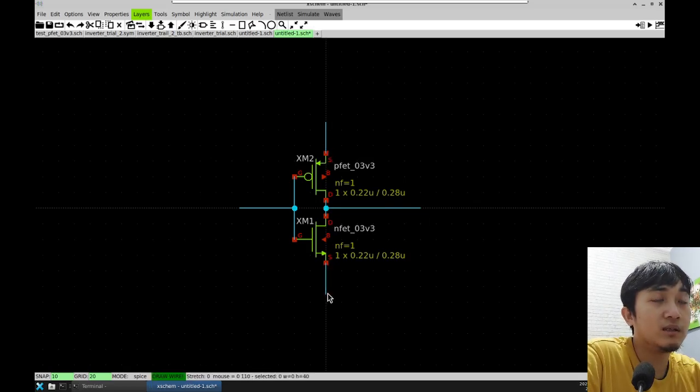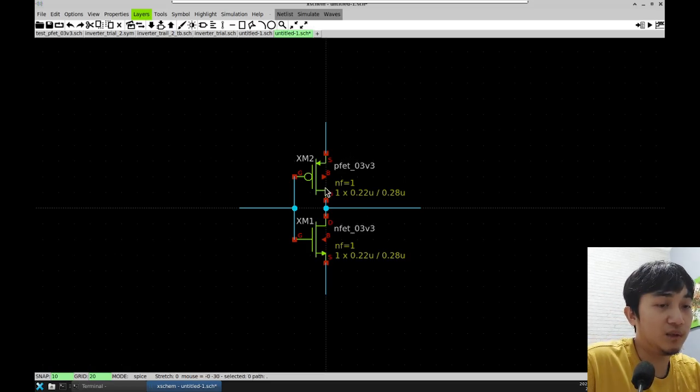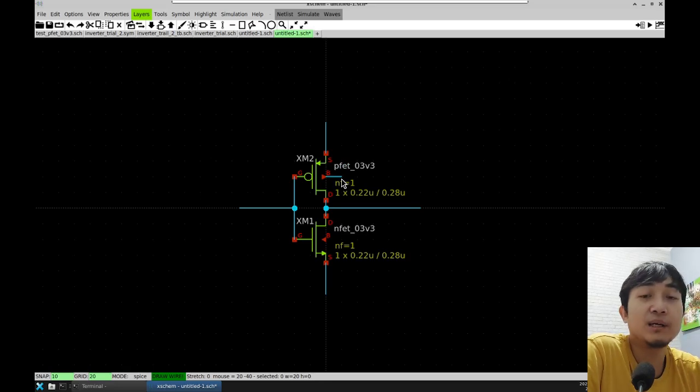and by the way, there are some differences between real world MOSFETs and these model MOSFETs. These model MOSFETs have 4 pins: your regular source, drain, and gate, and one additional pin named bulk. The bulk pin will act as your N-well, like the body of your transistor.